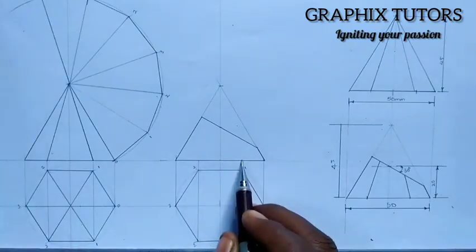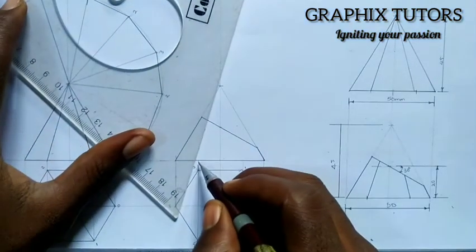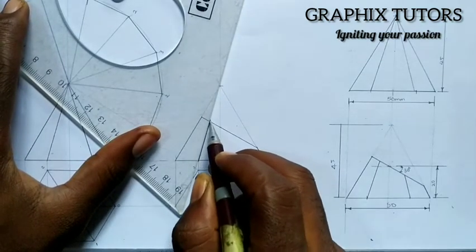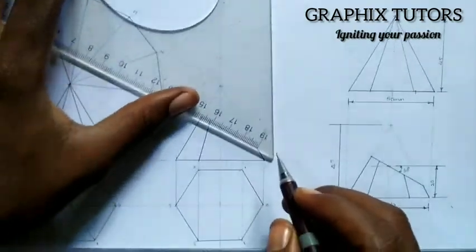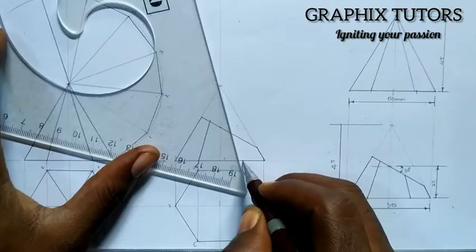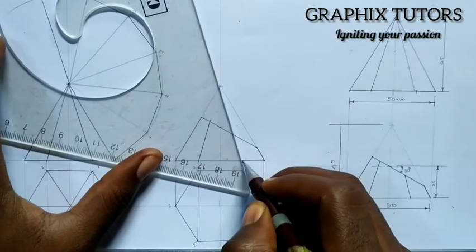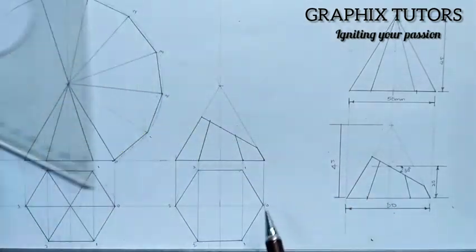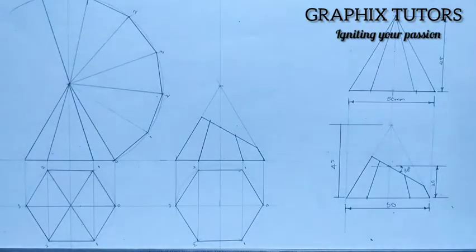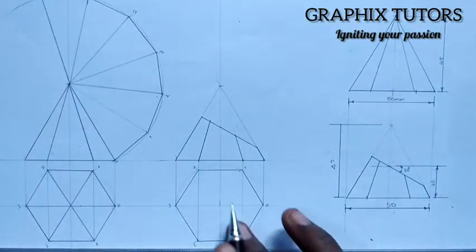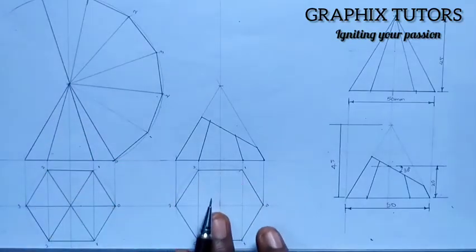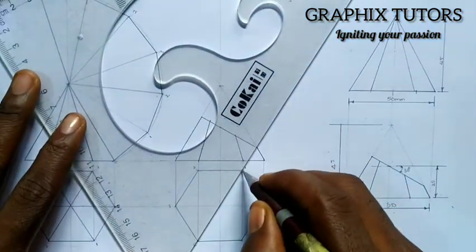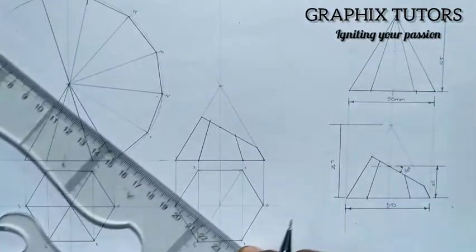All these points here, I have my line, I'll project them towards the center, just like what I did when I was developing a cone. But I'm not going to go to the center, I'm going to stop here. I'm heading for the center, but I'll stop at this. And I'll come here also, I'll do the same thing. I won't stop at the center, I will just stop at this demarcation here. Now after doing that, one thing you need to know is this is different from this. What I will do is draw my lines, join those 2 points together, diagonal lines like this, with faint line, not with thick line.